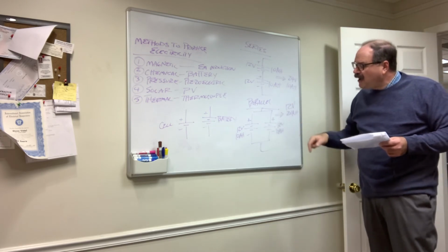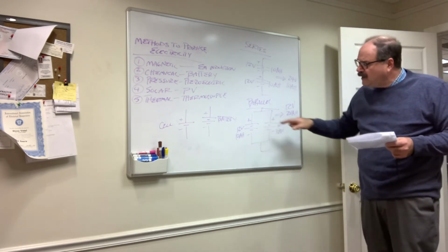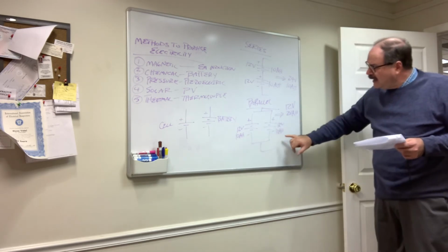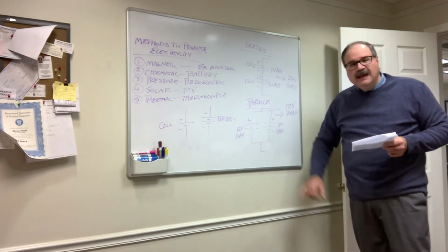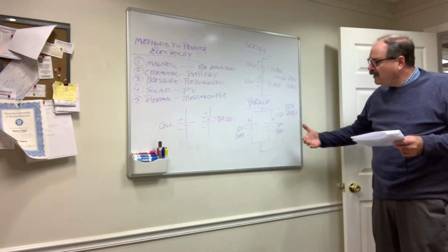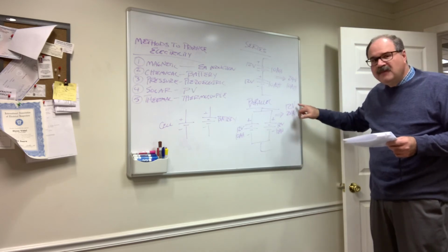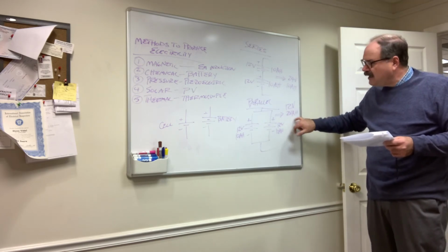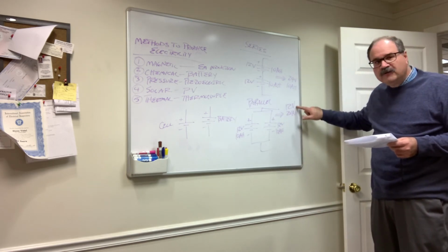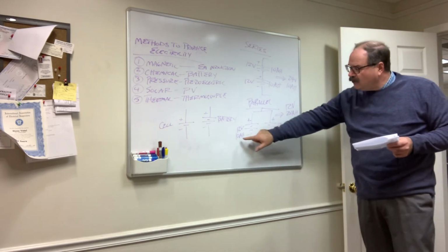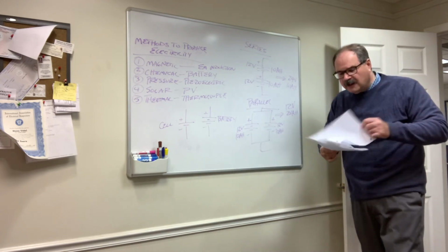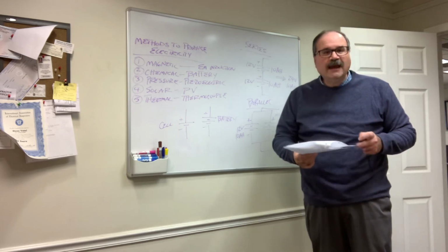And lastly, the parallel connection: when you connect two batteries in parallel, again, I have a 12-volt battery here and I have a 12-volt battery here. Each of the batteries has a current rating of 10 ampere hours. So in the parallel connection, the voltage remains the same, but now the current changes. So 12 volts in parallel with 12 volts gives us an output of 12 volts, but now 10 ampere hours plus 10 ampere hours gives us an overall current rating of 20 ampere hours.